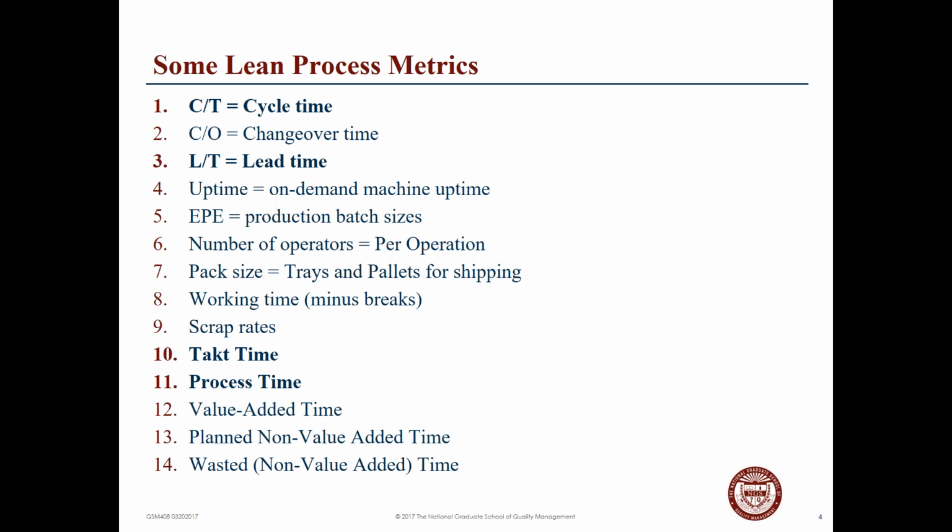Changeover time is another indication. If you're in an operation where there's tooling or equipment that needs to be modified or changed to deliver product, how long that changeover takes. For example, in an injection molding operation, when you move from one component or part to another part, you have to take the injection mold out of the press and set a new mold in the press, and then you have to make sure that your process is in balance by producing parts to standard and so forth. The time it takes to do that, depending on the company and the size of the machine, could be anywhere from hours to days.